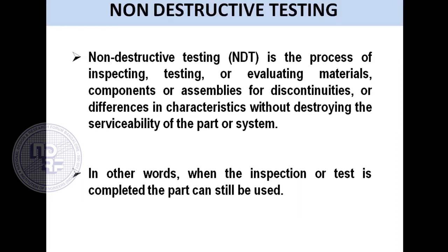So non-destructive testing is a technique where you carry out these tests at periodically defined intervals. An aircraft's life is measured in terms of hours or in terms of calendar period, like months or years. So after an aircraft has undergone a certain number of flying hours, like maybe 50 hours or 100 hours, as decided by the designer, testing of the aircraft is carried out as a preventive measure, so that you can detect any defect which has crept in during its usage, and necessary repairs can be carried out so that the aircraft can be put into use again.